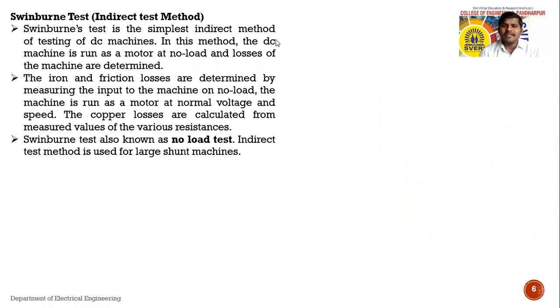In that test, the motor is run on the no load condition. Once the motor is run on the no load condition, we are able to calculate the losses of the machine. That means the no load losses can be determined by performing this test. Now, can anyone tell me what the no load losses are? Which are the no load losses?